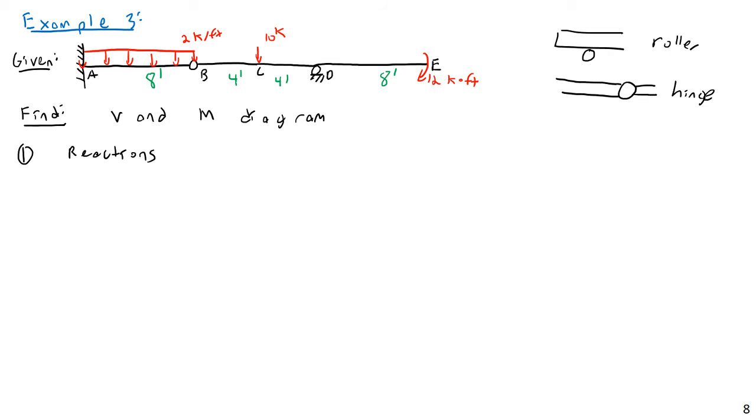We need to think back to what we did way earlier, toward the start of the year, when we looked at internal forces and finding whether things were statically determinate or not, and stable or not in frames and things like that. Remember how we always had to break things at pins, internal pins? We have to do the same thing here.